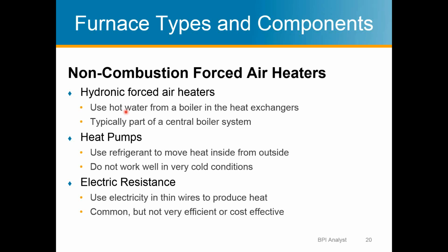So there are other types of furnaces out there. I primarily showed you gas-fired furnaces. There are also hydronic furnaces, and they can be forced air or not forced air, but they use hot water essentially instead of burning a flame and running it through the heat exchanger. It just puts hot water through the heat exchanger and then blows air across it, or it could just not blow air across it. It could be just a radiator in the room, which is a little more popular outside of California.